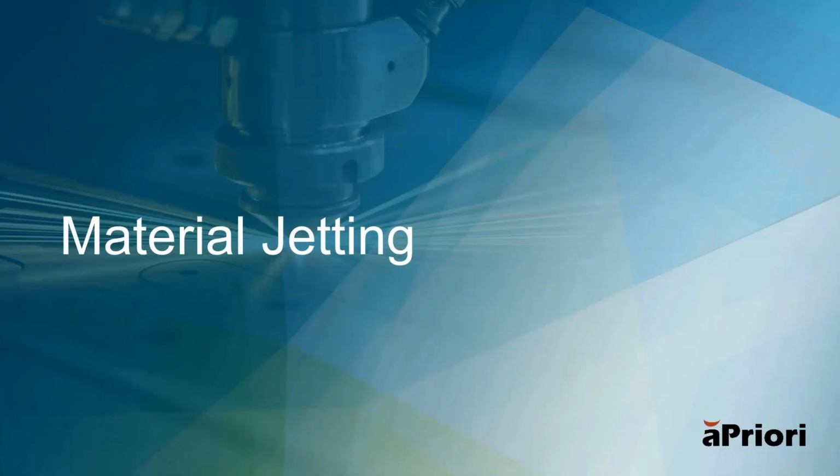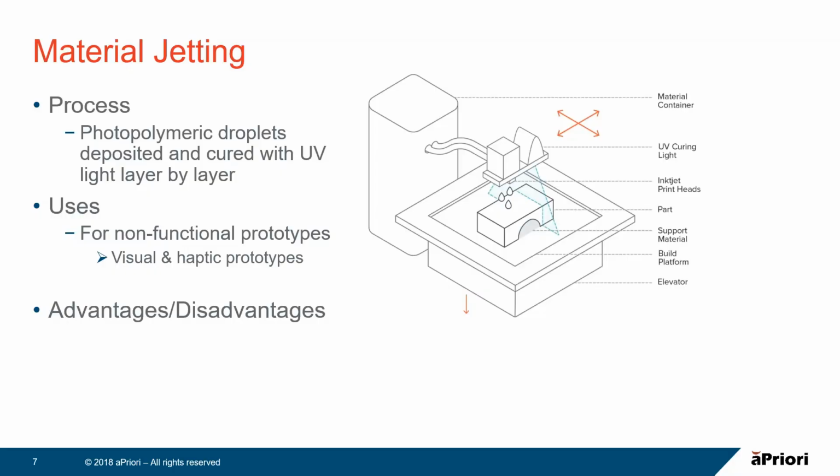Hello, everyone. So the first of the 4 processes I'm going to talk about today is material jetting. With material jetting, photopolymeric droplets are deposited from a printhead, and on the same printhead there is a UV lamp, and as the droplets are deposited, the UV lamp almost automatically solidifies and cures the droplets, and this enables the part to be built up layer by layer in the vertical direction.